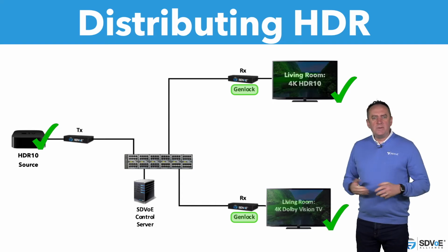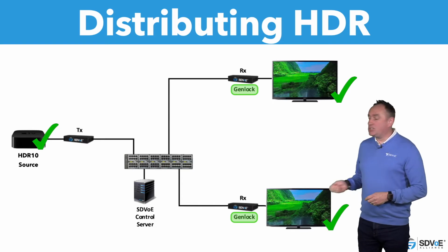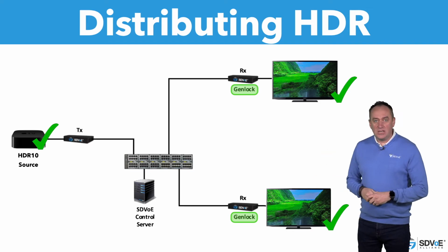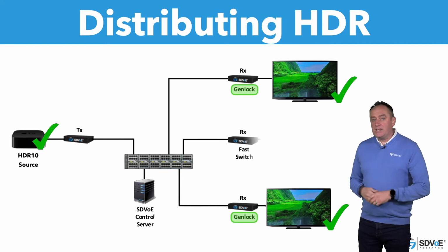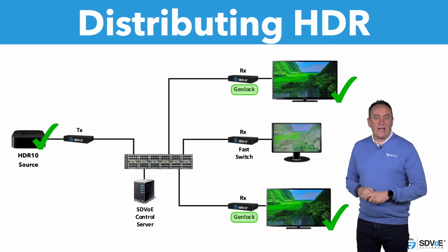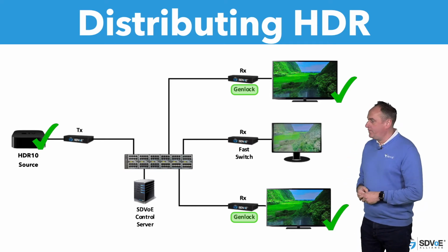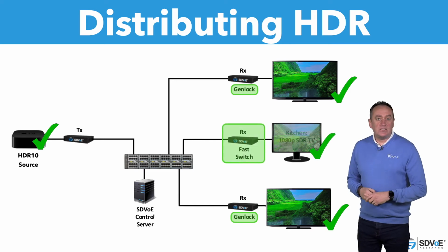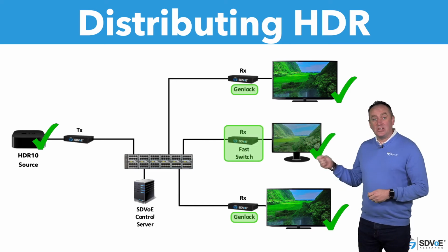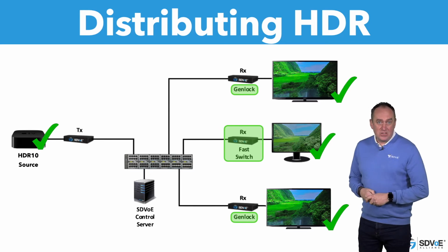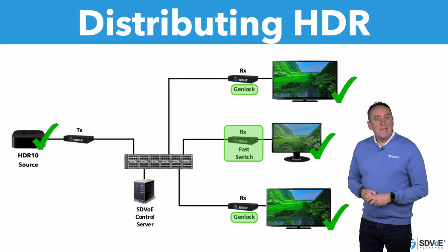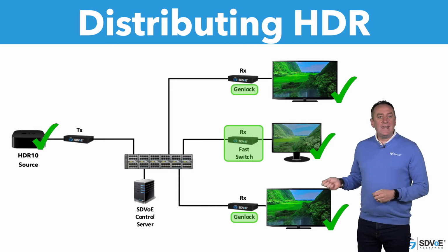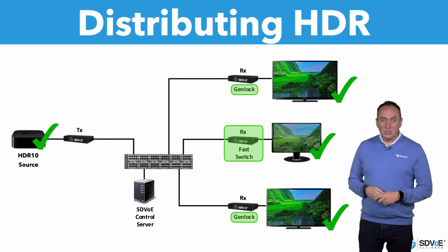However, what happens if we have a mix of HDR10, HDR10 Plus and non-HDR displays? Well, the answer is that the HDR displays will work fine. However, the non-HDR displays will look extremely washed out and get some of the colours wrong. SDVoE is able to correct this using techniques to convert the HDR signal to a standard definition colour space, which the older display can understand. The older display may also need some scaling too, which again SDVoE is easily able to provide.